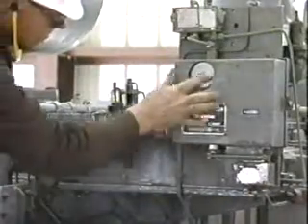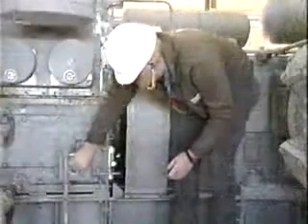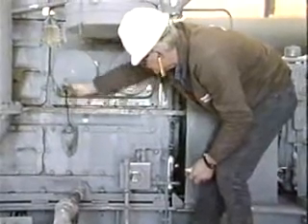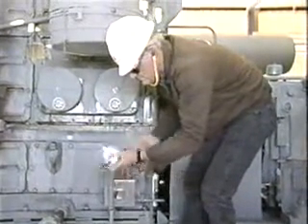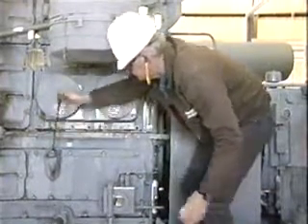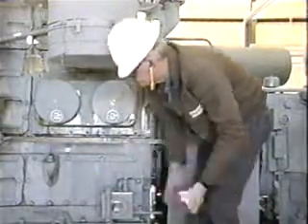Check the lubricant levels and pressures and record that information. Then check the engine crankcase oil level. Inspect the color of the oil to see if it is contaminated. For example, white or creamy colored oil would indicate water in the oil. Also inspect the pumps and injectors for normal operation.